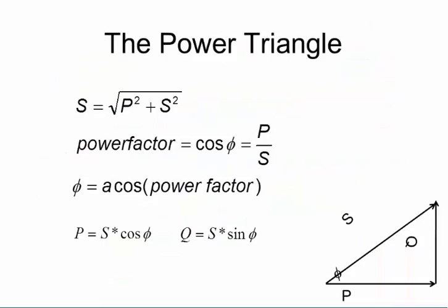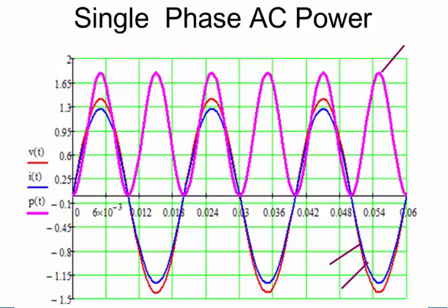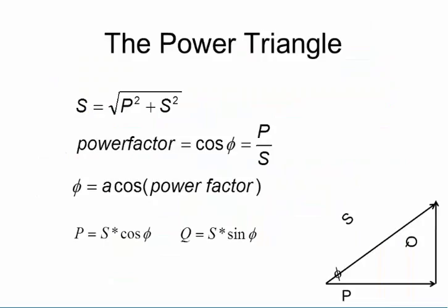So now what occurs is, depending upon the load, there may be a phase shift between the voltage and the current, and I'll just very quickly go through that. If the load was purely resistive, in other words, it had no ability to store energy, then the current and voltage would be aligned, just as you see in this way, so that the voltage and the current have exactly the same crossing points and the same values where they become a minimum or maximum.